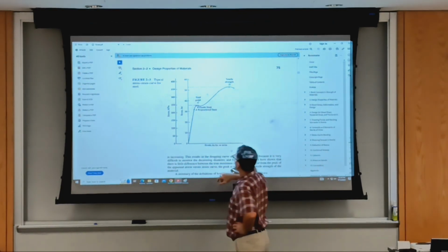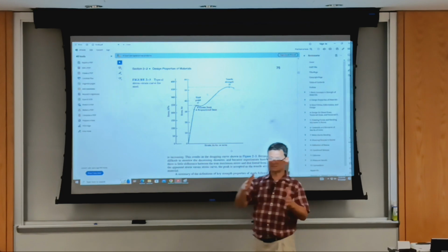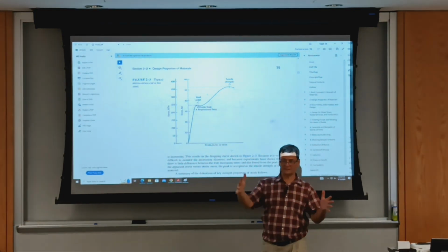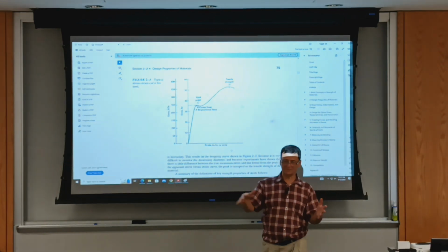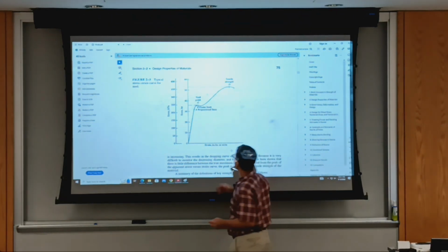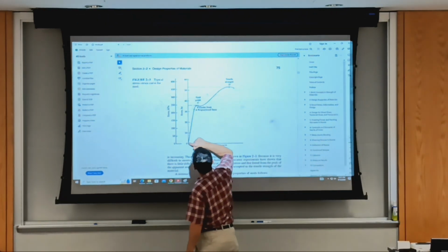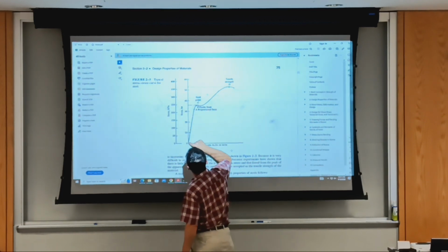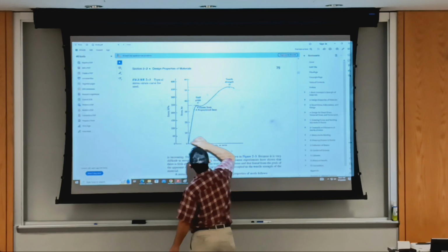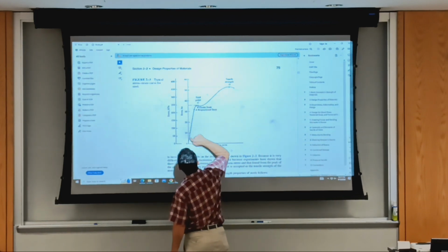And then the strain, which is unitless. It's the current length minus the initial length, divided by the initial length. That's the strain. And this is very steep, very close to vertical, so it's artificially moved away from the vertical line, and it's a straight line.